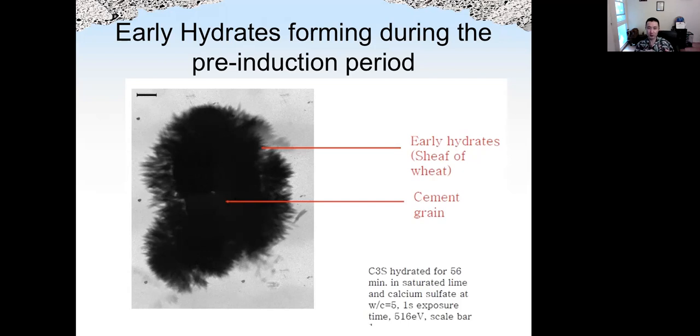For the hydration to continue, the water will continue to dissolve more cement and release more ions into the water solution. So that is the third verb, diffuse. Water will diffuse through this hydration product, get into the cement, and release more ions. These more ions will diffuse through the hydration product and get into the solution again. And then we have more precipitation, more hydration product. So that is dissolve, diffuse, and precipitate.